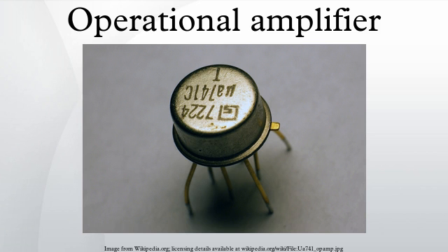When the desired closed-loop gain is high, op-amp frequency compensation is often not needed because the requisite open-loop gain is sufficiently low. Consequently, applications with high closed-loop gain can make use of op-amps with higher bandwidths. Noise, distortion, and other effects. Reduced bandwidth also results in lower amounts of feedback at higher frequencies, producing higher distortion, noise, and output impedance, and also reduced output phase linearity as the frequency increases.